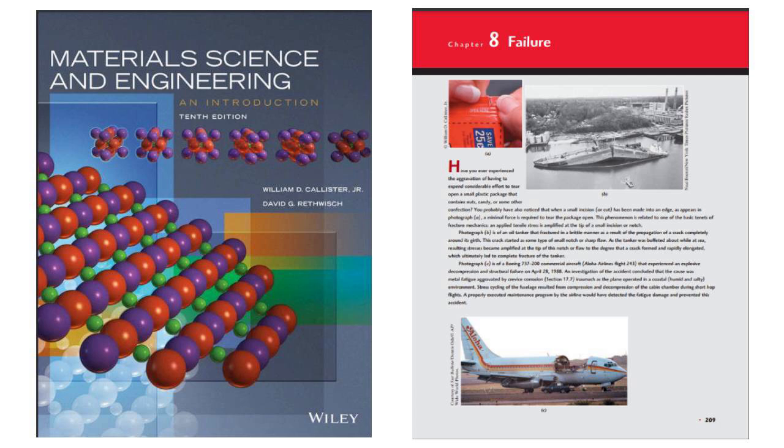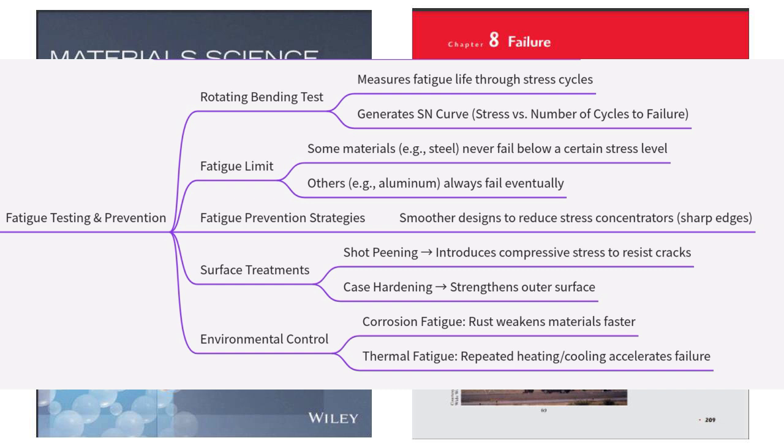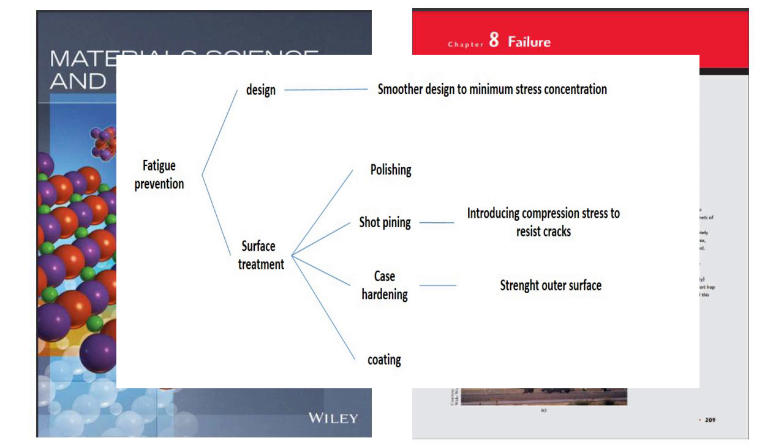But if we know how these cracks form and grow, can we do anything to prevent them in the first place? Absolutely. There are several strategies we can use to enhance a material's fatigue resistance. So we talked about design: minimizing stress concentration, smoothing out those corners, using gentle transitions instead of sharp, abrupt changes. So basically streamlining the design to reduce those stresses.